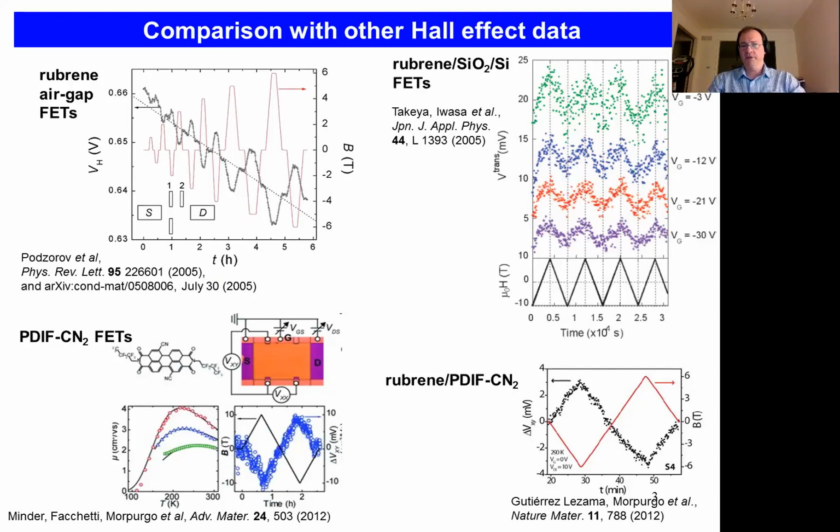On the other hand, even in the purest crystals, you have some residual traps that trap and detrap charge carriers, and these multiple trap and release processes cause fluctuations and noise. So the mobilities are low, noise is high, so we have this problem of signal to noise ratio as a result.